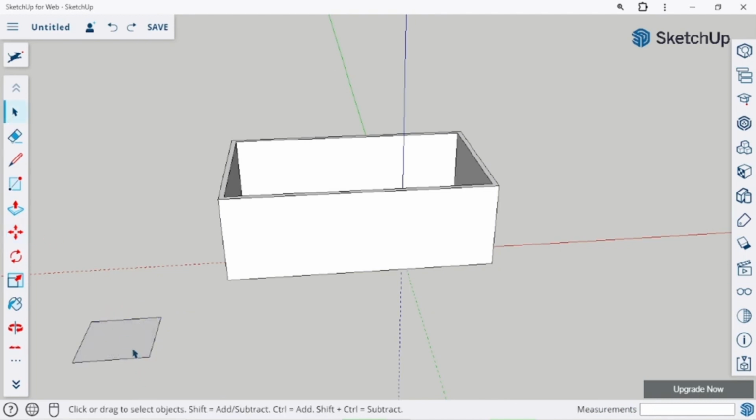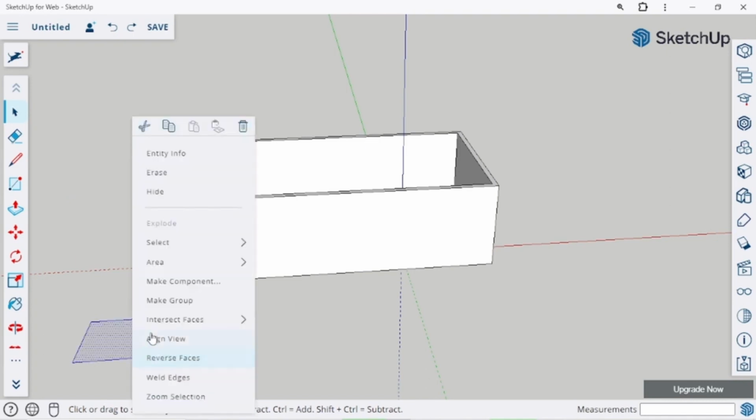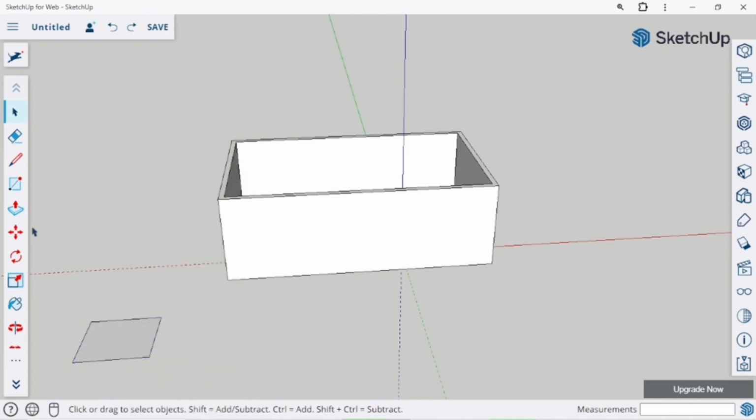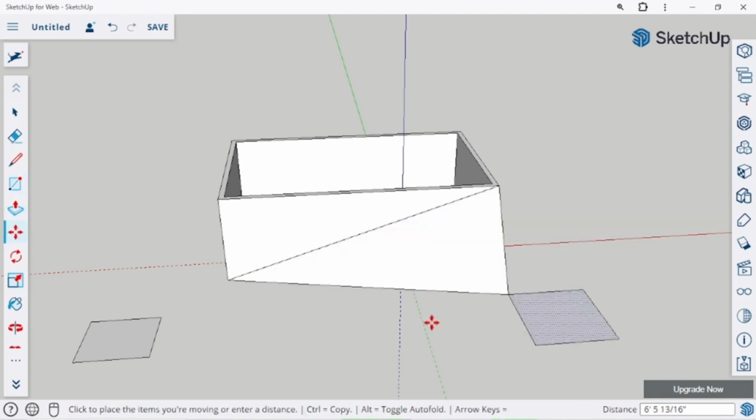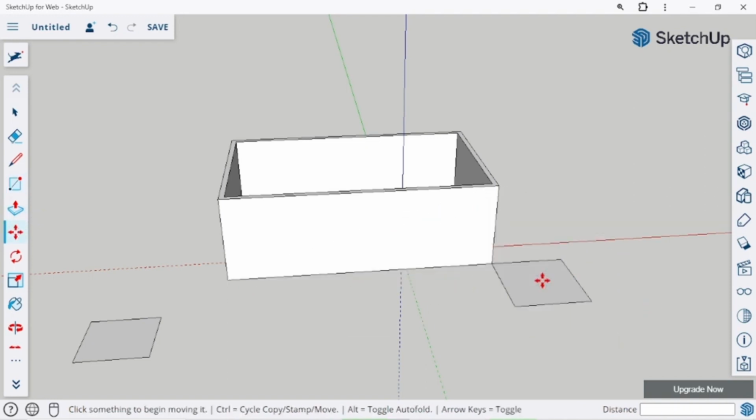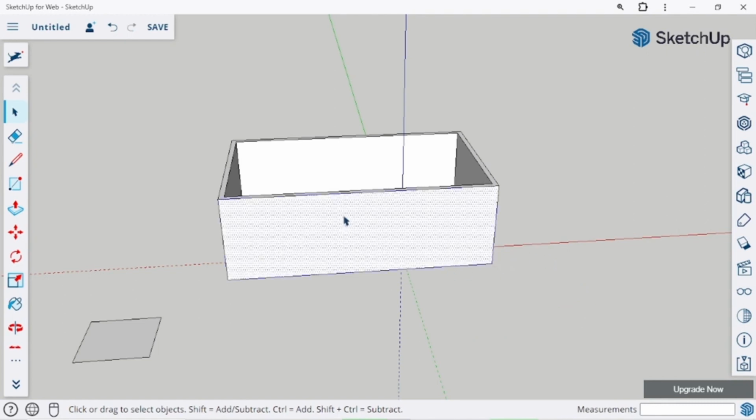By grouping, we triple click on it, then right click. So now let me use this for an example. We already have this view, then we draw it. Moving this one, you see it's making it a mess. So now let's end it, and then let's delete this, and then triple click on the plan to select everything. After that, we right click and then we make a group. Now let's test it again to see.